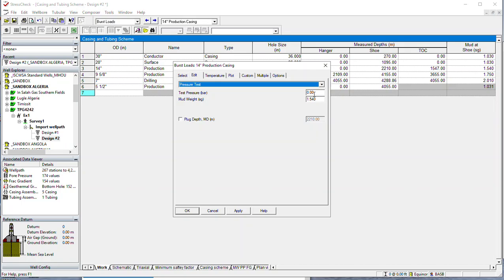The pressure test would be a result of the displacement to gas, and that should be 600 bar, and it goes up to 635 as we discussed in class. Any casing less than 16 and something would have a 35 bar added kill margin for bullheading, according to the NTNU requirements governing documentation set for casing design.